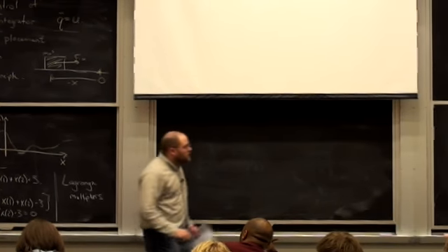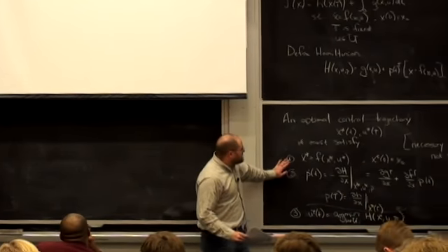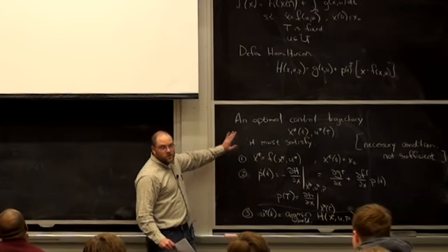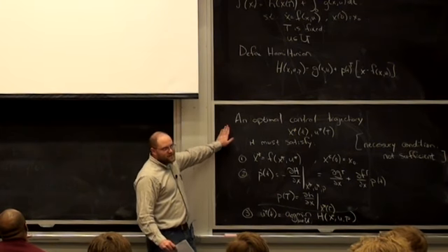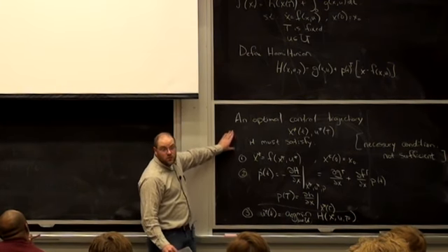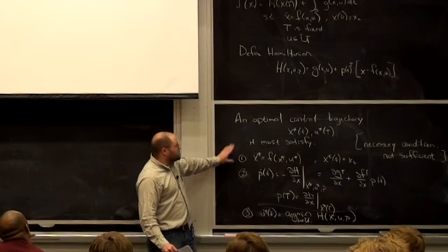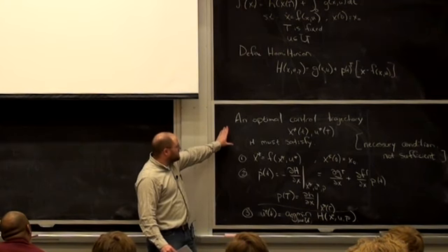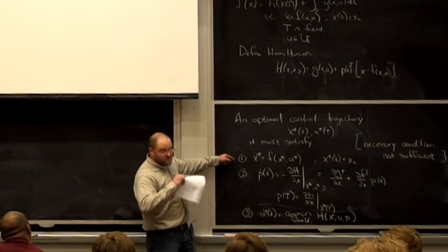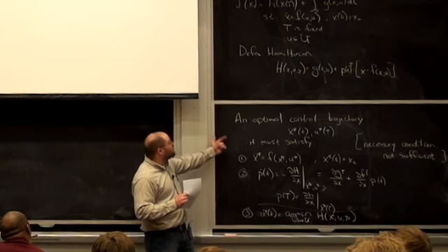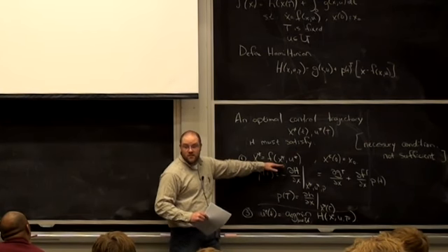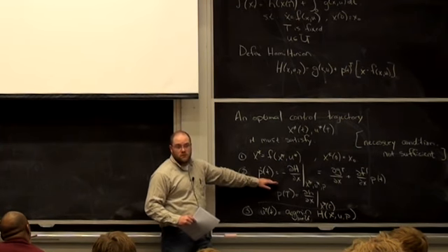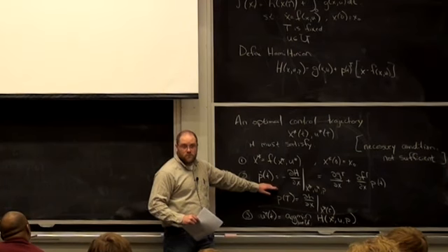What you're about to see is that all I'm saying in the Pontryagin minimum principle, which is an absolute staple in optimal control, is that J of x, which is my cost-to-go function, is at a stationary point with a Lagrange multiplier which enforces the dynamics. And that Lagrange multiplier happens to be p. So let's just see how that plays out.